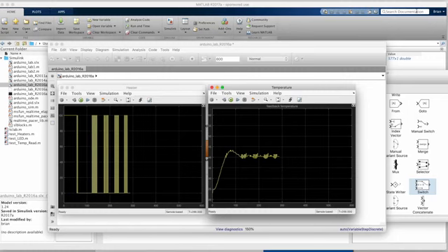The temperature rose faster this time since the heater was on full blast, but it overshot 40 degrees before settling back down and hovering around our set point. Why would this controller overshoot? It doesn't make sense that the temperature would continue to get hotter after we stop supplying heat, right?